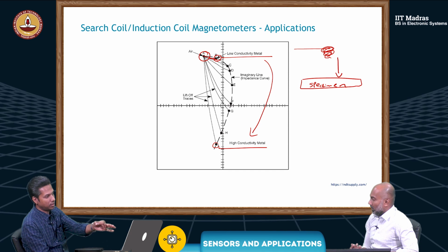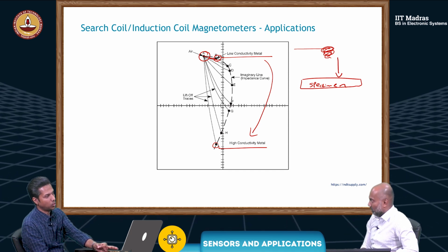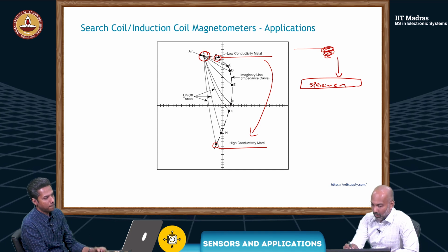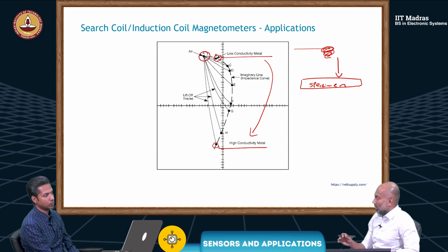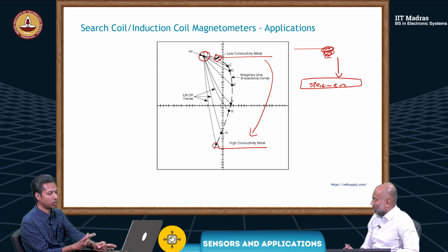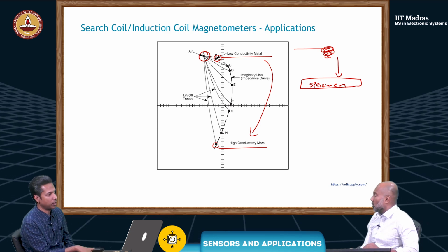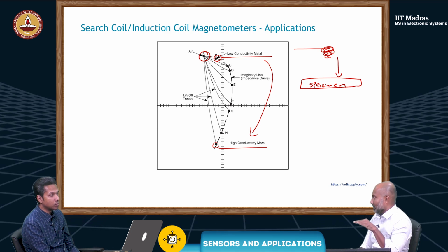Then you're bringing it close, on top of the specimen, where you measure it, and then you measure the impedance. I got B. And now you get specimen C, another object. The coil is at the same place, but you're now comparing that to that reference value. Which reference value?